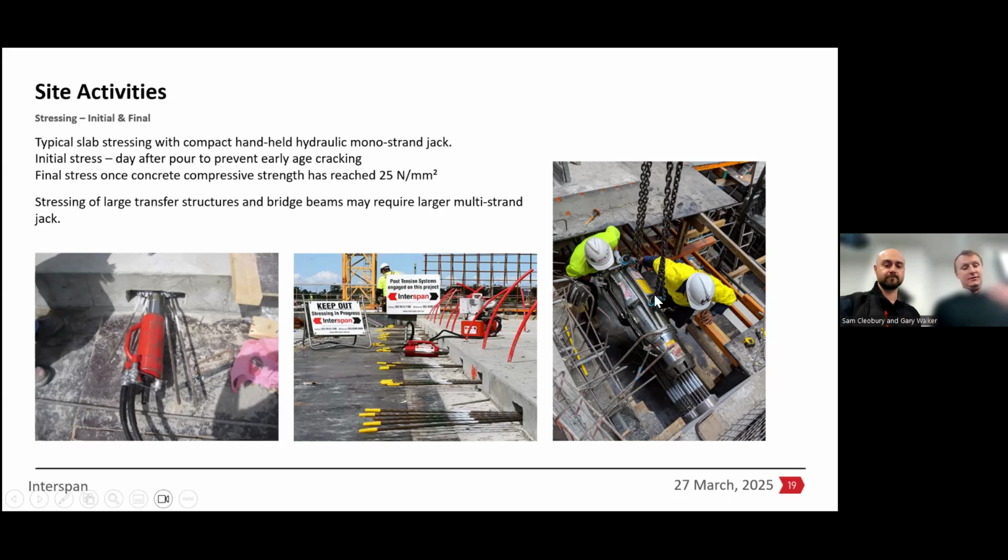The issue with this in a beam, in a building situation, is that you can see the size of it. You normally need to leave a pocket out of the slab around it so you can position it into place. You need a crane to hold it in place, so you're using the crane for probably a day, because it's fiddly to get it into position and onto the ends of the strands, and then you've got extension checks, so you don't want to move it out and try and get it back on. So you've got a day typically out of the crane.